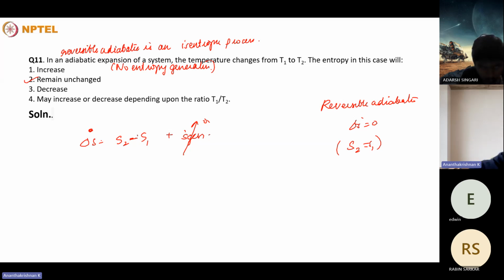Okay. So you mentioned about liquids, right? For the entropy change. Last year in GATE, a question was asked for a liquid where the wall is adiabatic or insulating, and the two temperatures T1, T2 are given. I calculated Q equal to MC delta T, though it was wrong because they mentioned insulated. I did not see the term. So Q equal to 0. Yeah, Q is equal to 0.